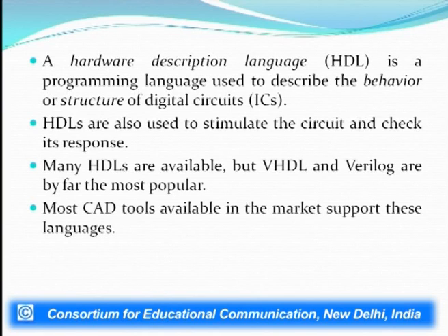The circuit can be simulated by giving it signals similar to the signals expected in the real world, and the timings and the response of the circuit can then be assessed, and it can be determined when the circuit is going to be physically working and how it is going to function. Now, many HDLs are available for this purpose, the most popular ones being VHDL and Verilog. Most of the CAD tools available in the market support these languages. Today, we are going to be focusing mainly on VHDL.